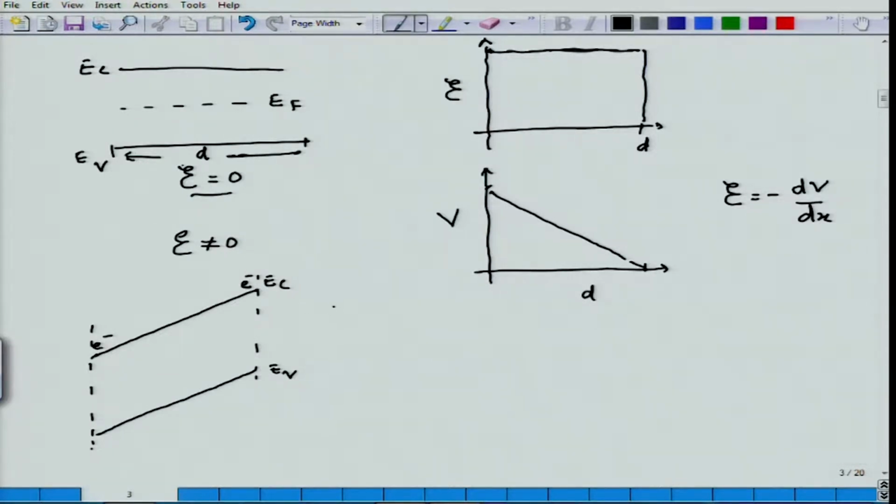And since this is an energy band diagram which, if you recall, is plotted for electron energy increasing in this direction, the energy value increases for holes in the opposite direction, and hence for the hole this is higher potential and this is lower potential, because band diagrams are plotted for electron energy.